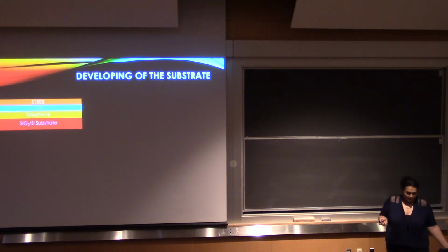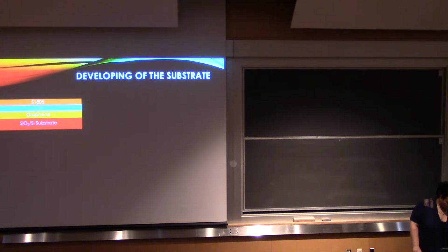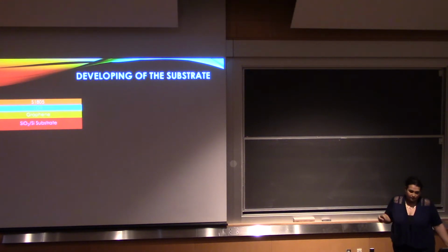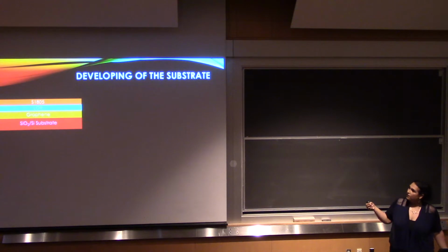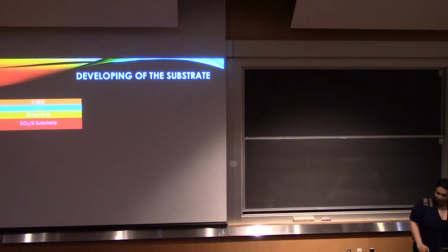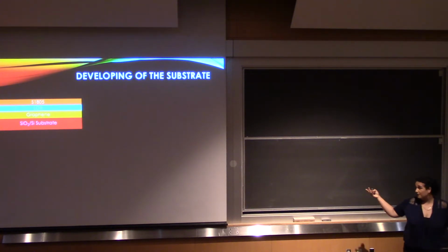So there is a substrate, silicon dioxide on silicon, with a layer of graphene on it. Then we have a bilayer resist on top of it, where one layer is LOR, lift-off resist, and the top one is S1805. S1805 is the photoresist that I was talking about, which becomes soluble, and the purpose of LOR is to help with the removal of the layer of metal contacts, which I will talk about later.